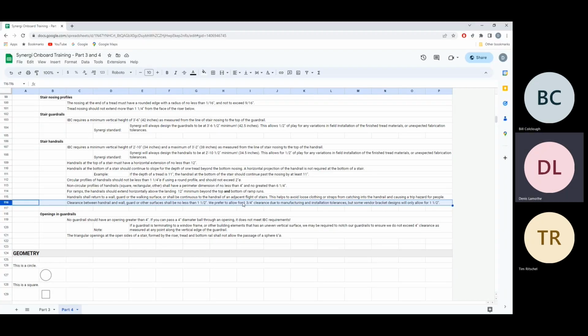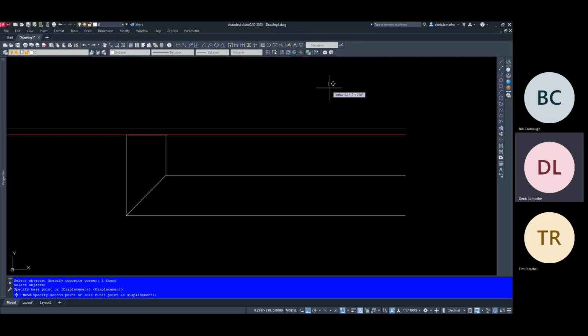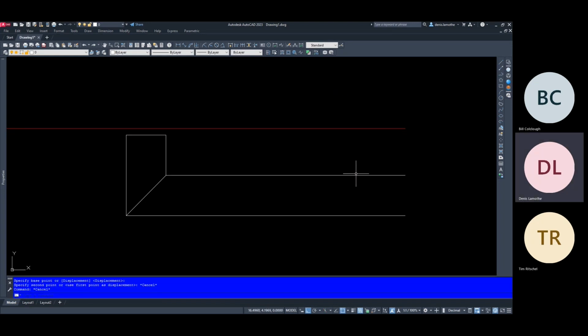Yeah, 1.5 inches. However, like I mentioned, there could be some inconsistencies in the wall that could move in or out. So we'll try as much as possible to build in an extra maybe 1/4 inch. So instead of 1.5 inches minimum here, let's see if that dimension line pops up decently. Yeah, I might instead show it to be 1.75 inches. And so if there's any variations in the wall, it doesn't creep into that 1.5 inches. We'll still have some safety margins there.